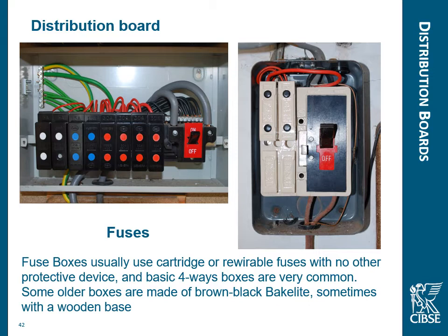Now the fuse board on the right, albeit a small one, shouldn't really have any of these in your buildings now, but if you have still got the odd ones, think about the fact that these contain asbestos. Behind the fuse carrier, these are rewirable fuses, and to protect the fuse carrier from the little explosions or the red hot wire that used to happen in there, we tend to have a strip of asbestos.